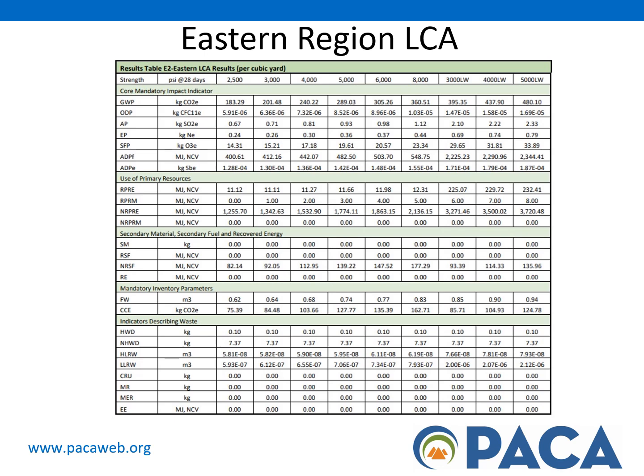The target most specified is global warming potential, and as you see, it is reported as kilograms of CO2 equivalent. Remember, these numbers are averages of the study. Some concrete mixes had higher or lower global warming potential results. Many specifiers have targeted a percentage of the average as a starting point for global warming potential targets and goals.